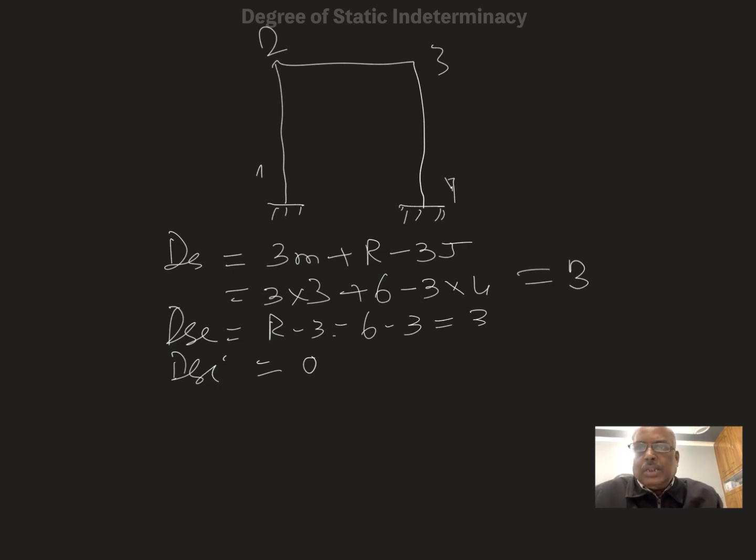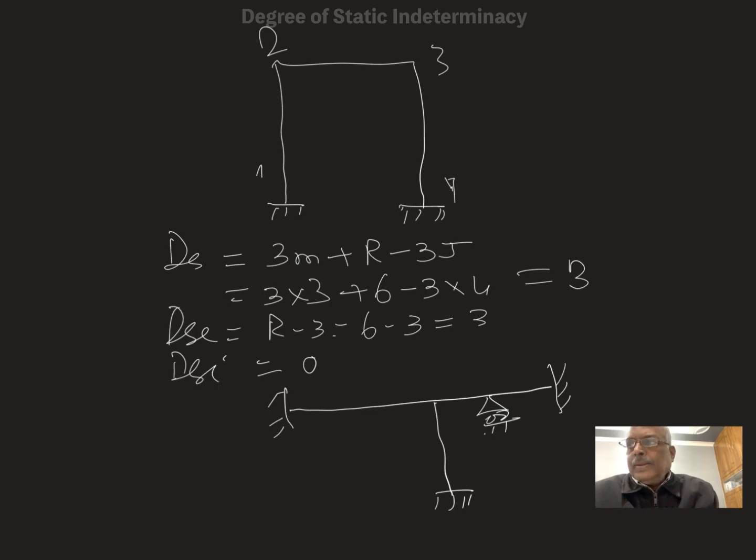Now I am going to take another example. Roller, and suppose the hinge here, and we are going to find it by the method of joints as well as by Henderson's rule. By Henderson's rule, this will be r dash 1, r dash 2, and we can cut it here, one cut here, one here, and one here. 3 cuts to make a tree-like structure.